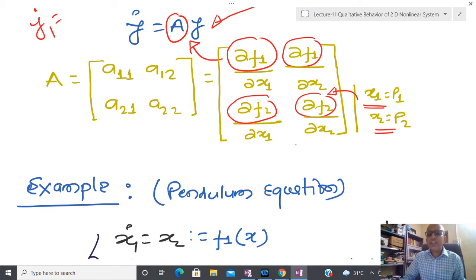say in a quantitative way, I cannot picture it out, and due to that reason I do not know up to what range this linearization technique will work. Most of the time the nonlinear control community suggests that linearization technique is very restrictive. So whenever you are using that, please try to operate your system very close to the equilibrium point. If you deviate a little bit, then you are not able to understand the property of the resultant system. Okay, now